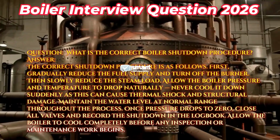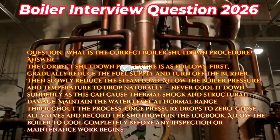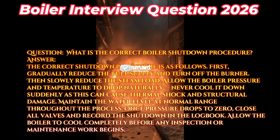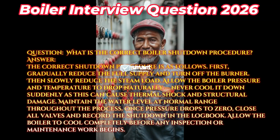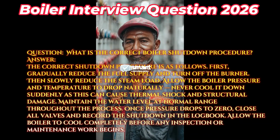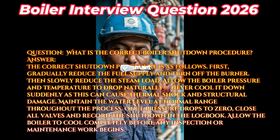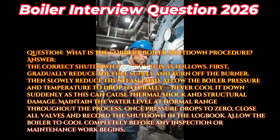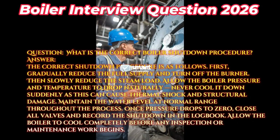Question: what is the correct boiler shutdown procedure? Answer: the correct shutdown procedure is as follows. First, gradually reduce the fuel supply and turn off the burner. Then slowly reduce the steam load. Allow the boiler pressure and temperature to drop naturally. Never cool it down suddenly, as this can cause thermal shock and structural damage.